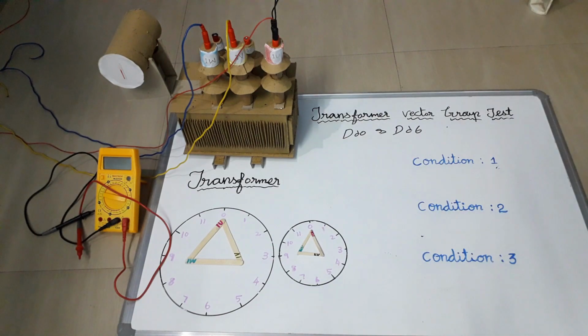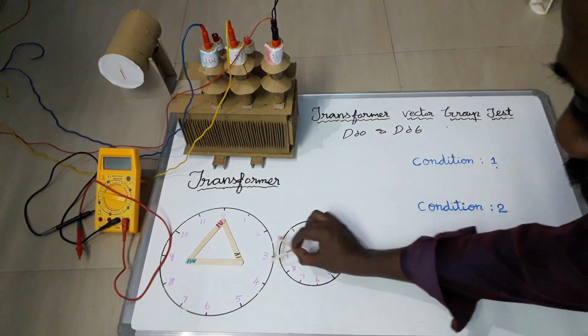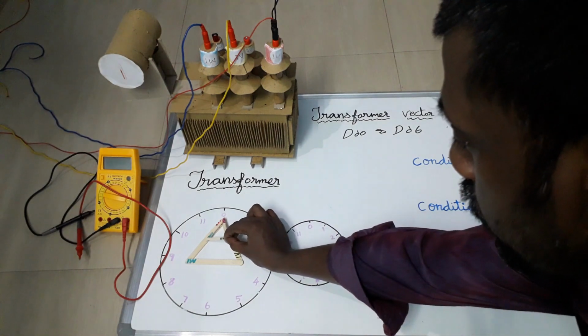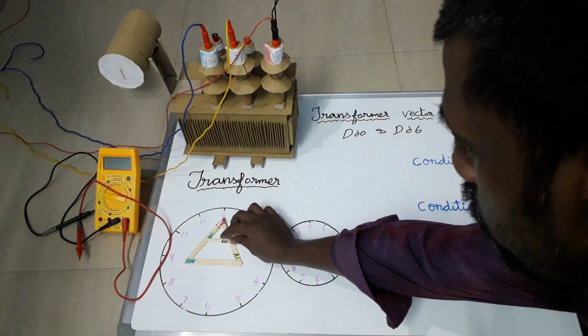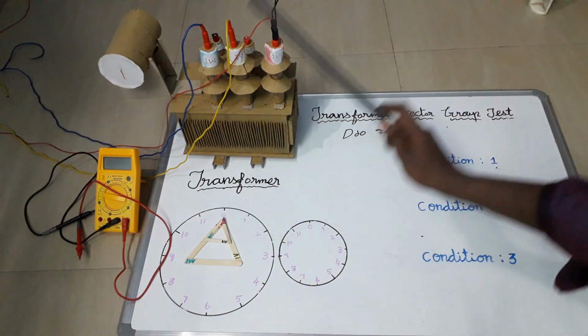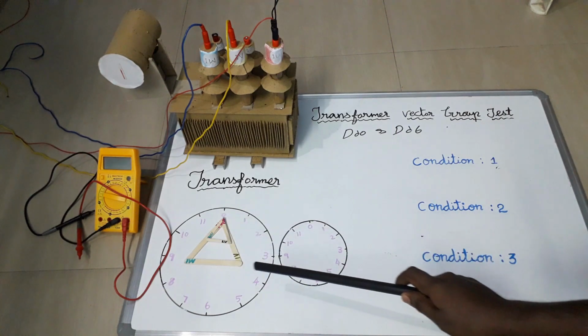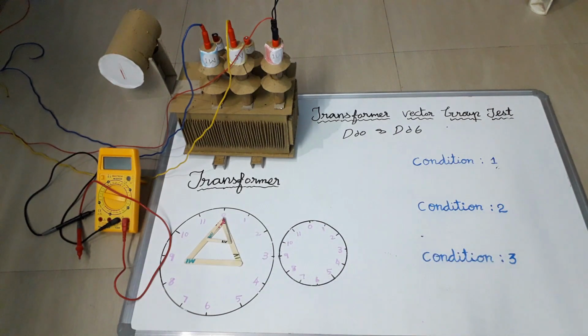Now for making easy testing, I am going to merge this LV with HV. Just check this. I am making 0 vector group over here. That is 1U and 2U shorted. So our connection will be similar to this.